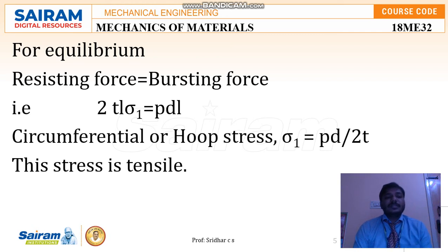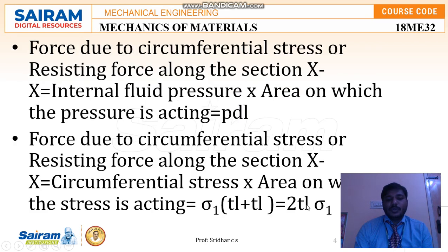The resisting force depends upon the material, as the cylinder is designed to withstand the force, but the bursting force is created by the internal pressure. The resisting force we got in the previous equation is 2 into t into L into sigma c, and the force we got is PDL.